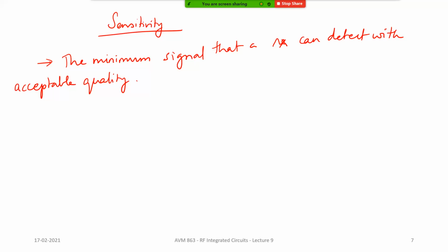Now, for example, if you look at your cell phones, like your smartphones, you can go to about phone, and look at the signal strength. If it's showing minus 80 dBm, minus 85 dBm, minus 60 dBm, minus 75 dBm, and you're still able to talk to somebody or use your data, it means that the receiver is able to work with such tiny signals and still have a successful communication, right? So suppose that signal power drops to minus 90.